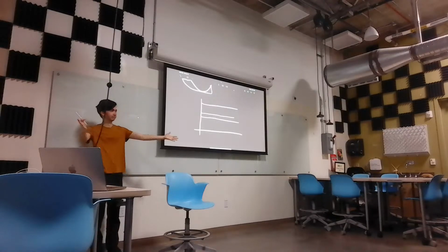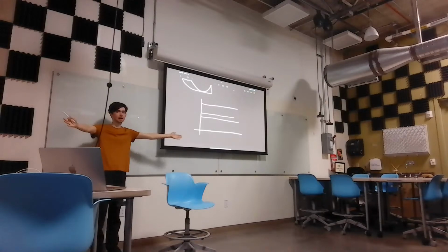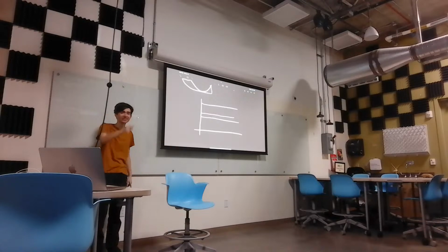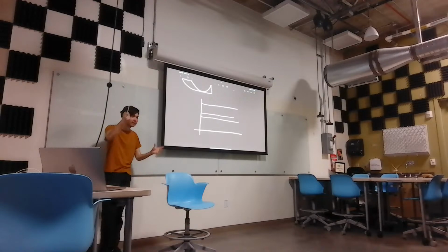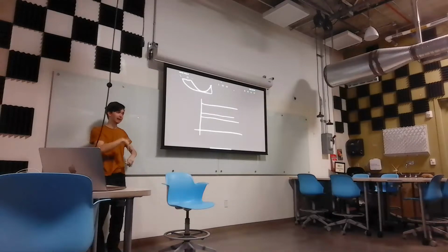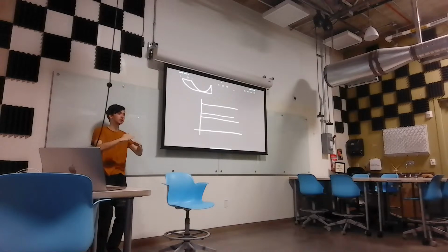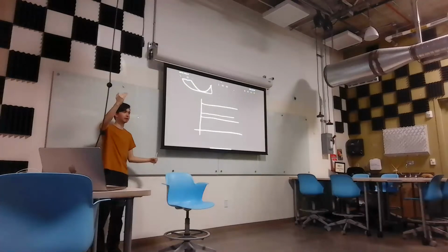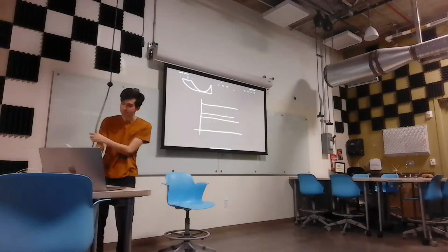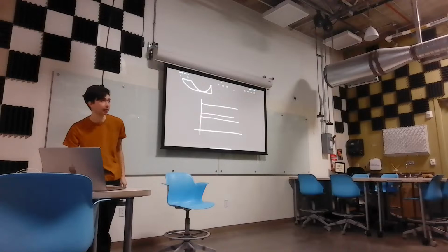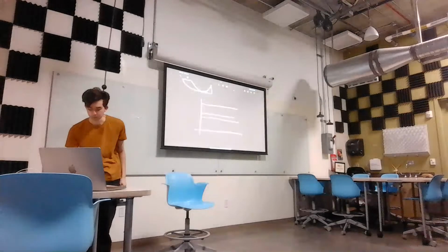What is the I in the PID? Who knows? What's the I? Integral. What that means is, as an error exists over many time steps, we accumulate that. So hey, the error is building, we've got a big old error here. So consider if we're at this bottom voltage. The error will very slowly be negative, right? Like that.